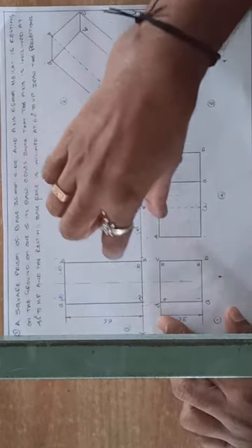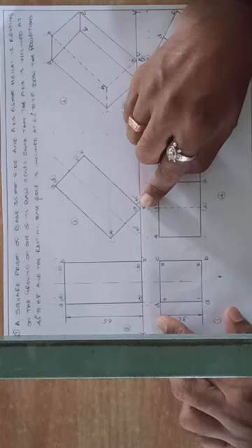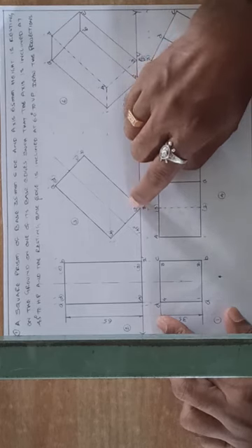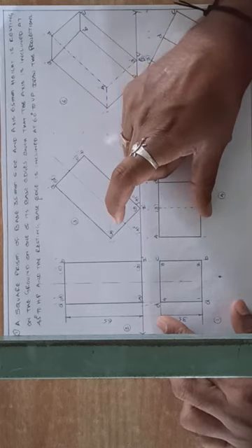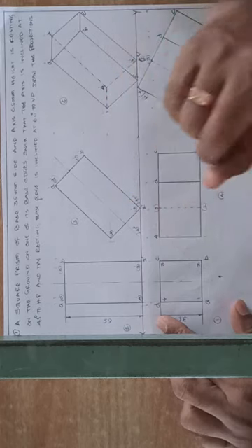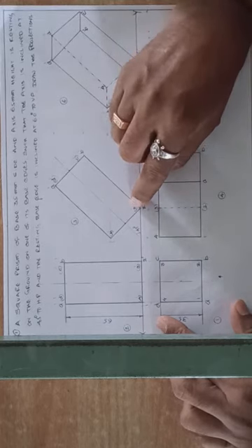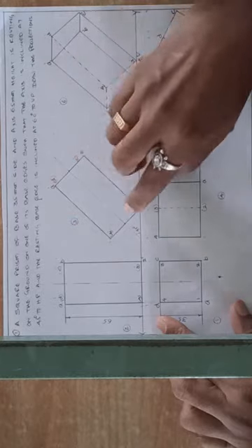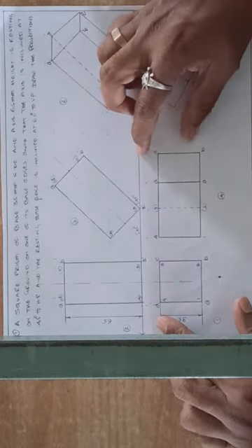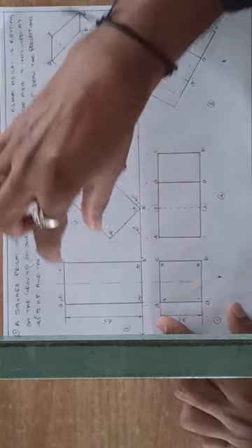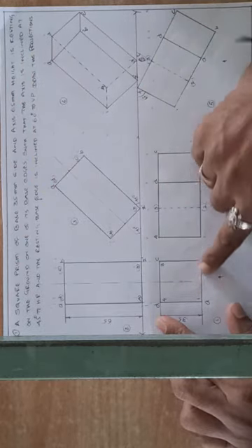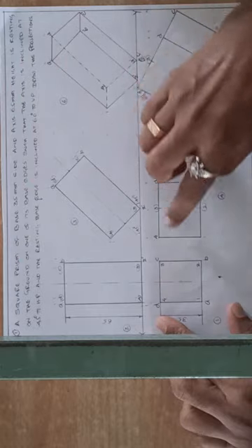So when it is tilted, now 2 is on the ground. Now here there are two points, that is 2 dash and 3 dash. That means when the object is resting on edge, it will have 2 points. Suppose if it is resting on corner, it will have only 1 point. So now 2 dash 3 dash means your condition is correct. Now rotate the front view to this angle, then vertical projections, horizontal projections, same notations transfer here, A horizontal, A vertical, B horizontal, B vertical, similarly C and D.